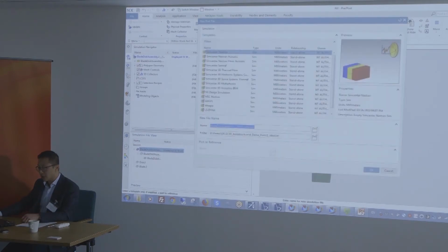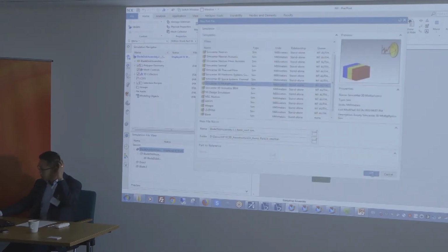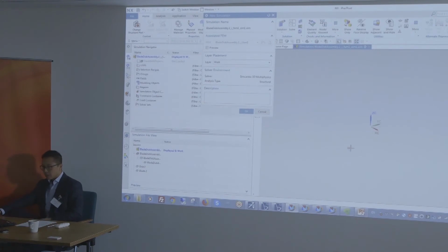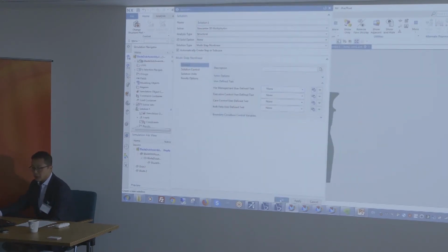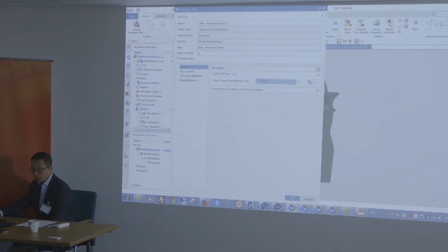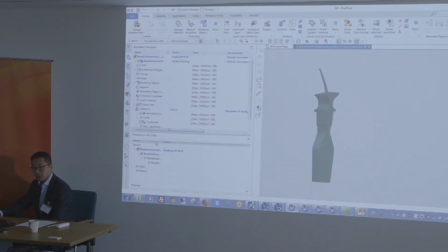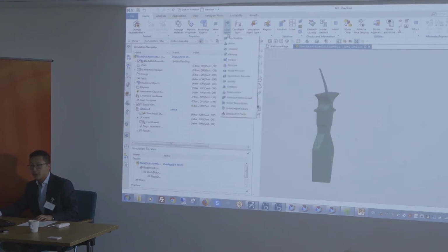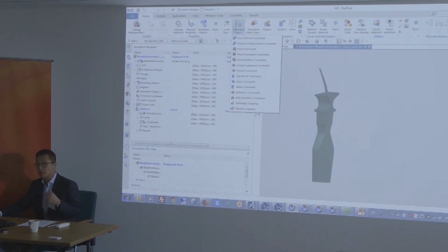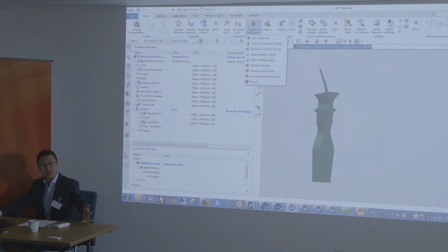Then we can go at the simulation level and run the multiphysics solutions, for instance. So in this multiphysics solutions, that one's particularly useful because it combines structural boundary conditions and also thermal boundary conditions. And all of the boundary conditions are kind of intent-driven. So there's always a meaning behind those. It's not just fixing this and that degrees of freedom, but it's more explicit.